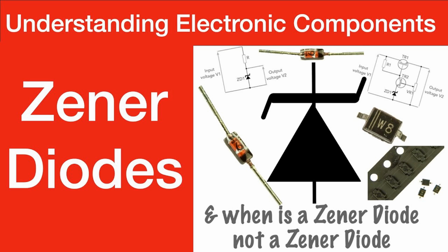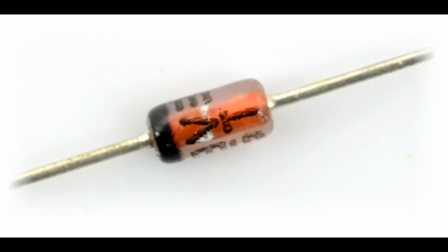6. Low-noise Zener diodes. Description. These Zener diodes are optimized to produce low noise during operation, making them suitable for sensitive analog circuits. Characteristics. Reduced noise characteristics compared to standard Zener diodes. Often used in low-noise amplifier circuits and precision analog applications. Applications: low-noise voltage references in audio equipment, instrumentation, and communication systems.